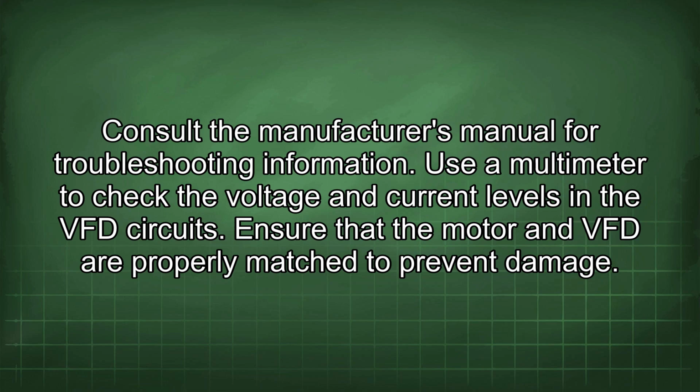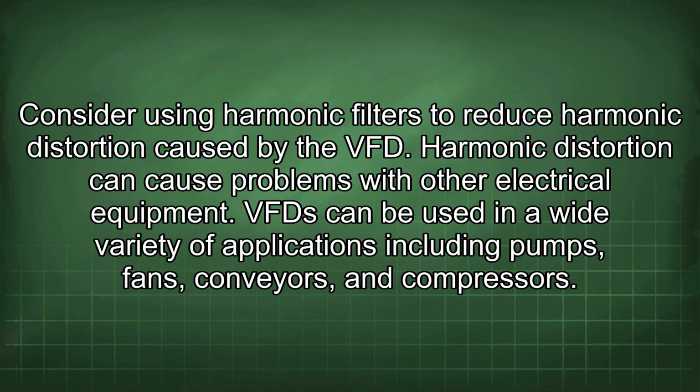Ensure that the motor and VFD are properly matched to prevent damage. Consider using harmonic filters to reduce harmonic distortion caused by the VFD. Harmonic distortion can cause problems with other electrical equipment.